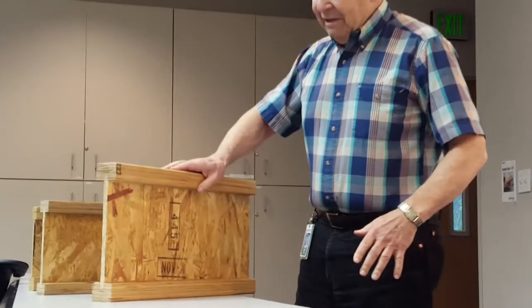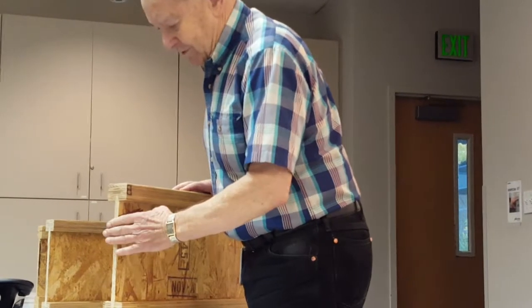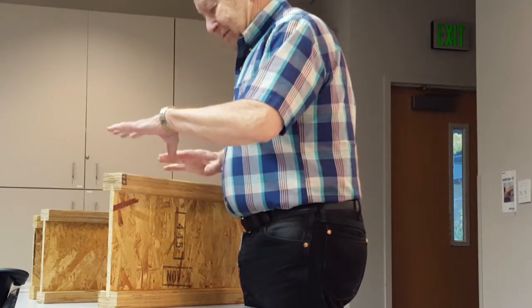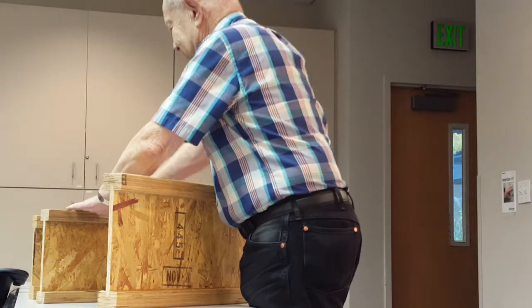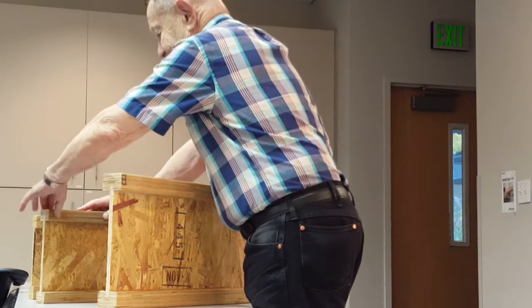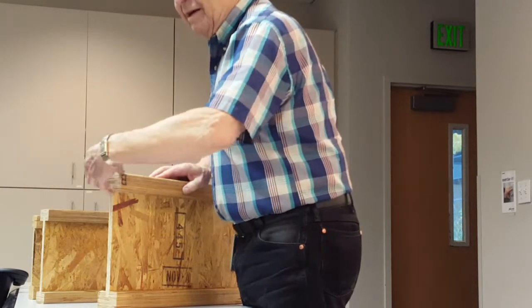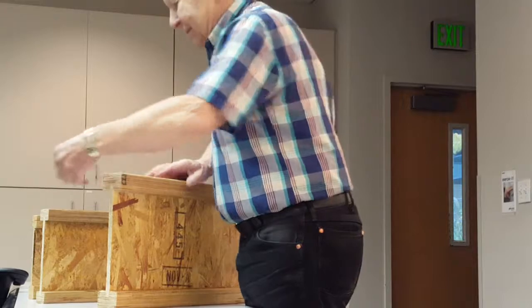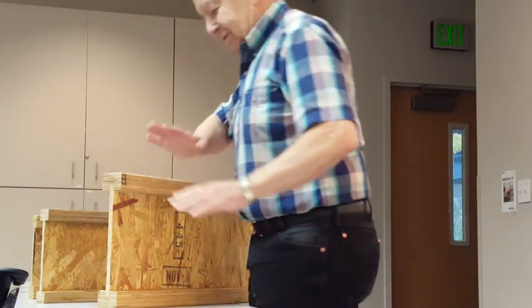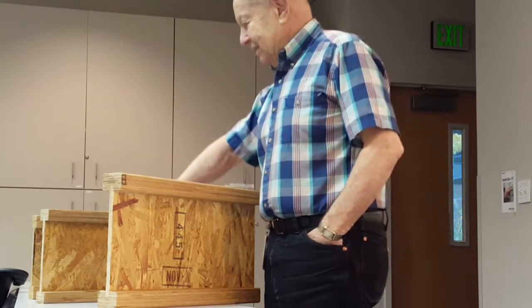Well, what makes most of the difference in the computation of the moment of inertia of the cross-section, where this one is quite a bit bigger number than this, and this is quite a bit more than that, is actually the size of this upper rail, because you're multiplying y squared times all the little areas here, and the same here and there. So this is rated at 5,000 pounds load, and this is 3, and this is 2.